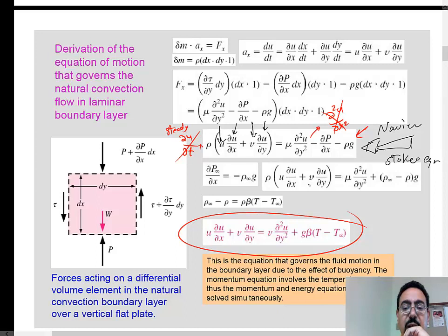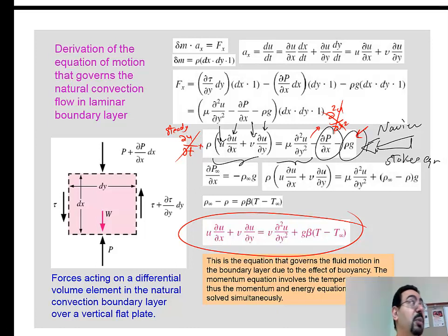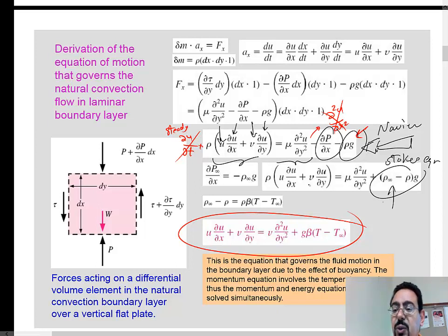But it has the convection term, and it has this diffusion term, or the viscous term, and it has the pressure term, that's a source term, and it has the gravity term. It basically says, because of your weight, the earth will pull you down. The gravity field will take you down because of the mass. It's this source term that will actually drive natural convection, because the density will change. All right? So he can change that density to temperature by beta. Remember, beta was 1 over T? And so he can change that term to beta.